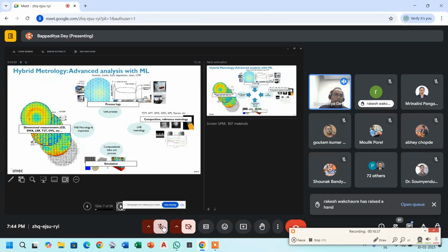So that is basically metrology data. Lab metrology is basically you do a lot of XRD, TEM acquisitions, SIMS, Raman effect. All this data is coming from, generally, the inspection also, and then you did a lot of simulations. Simulation means, okay, what are the different process steps that I will combine to define the process, and what is your spec length in this.